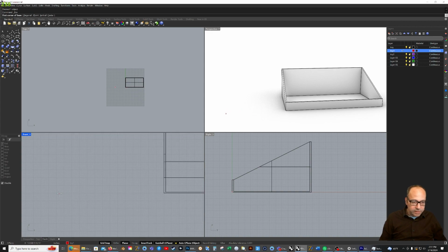You can move it into place later. So I'm just clicking on the corner. Now this toy is 10 inches wide. Now I'm in the front view. So the first one is going to be the horizontal, so 10. Then I have to hit enter. Now that's locked into the 10 inches. Now I know it's supposed to be 8 inches tall. So while I'm still in that front view, hit 8, enter. Now that's 8 inches tall.